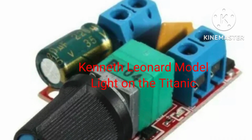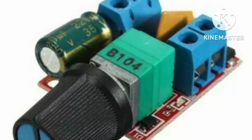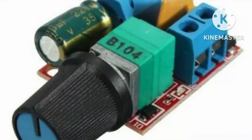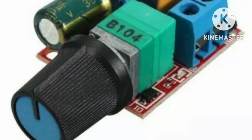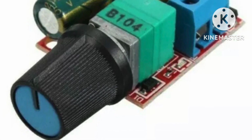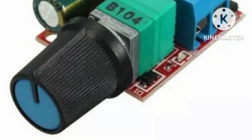So this board essentially turns its output on and off multiple times per second. This is actually a 10 kilohertz PWM generator, which means that the output of this board turns on and off 10,000 times per second, or 10,000 pulses are generated per second from this board. Now that's all very well, but it doesn't really explain how it allows us to brighten or dim our lights.